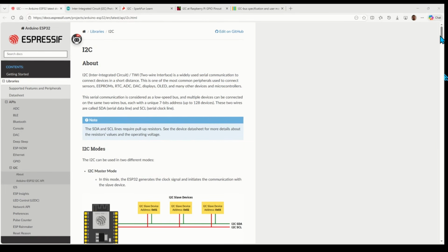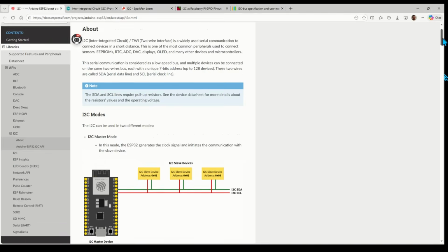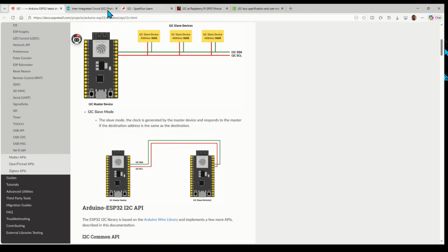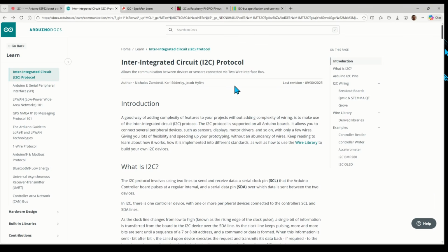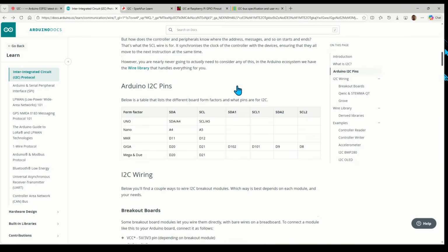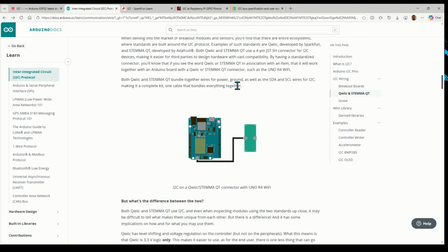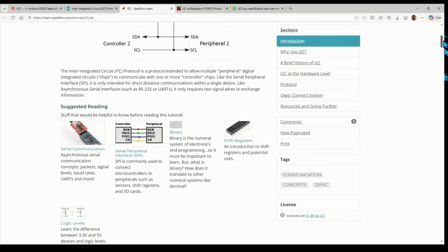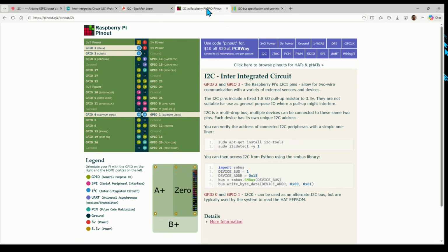This sensor uses I2C, which is a popular, simple serial protocol for small devices to communicate over very short distances. It uses two wires, clock and data, to create a multi-drop bus, allowing many devices to communicate, each with a unique address. The controller polls the address and that device responds.